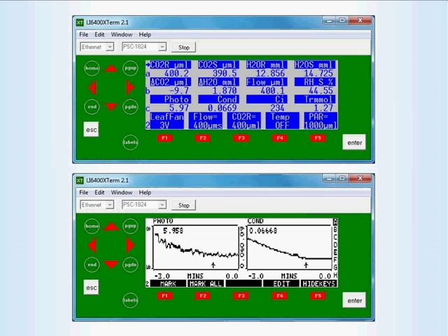We then reduced the leaf chamber mixing fan speed from the fast setting, which is a 5-volt setting shown previously, down to a value of 3 volts, shown here above the function key F1 in the upper display snapshot. The point at which the mixing fan speed was reduced was marked by an arrow in the strip chart using the mark function that you can see in the lower display.